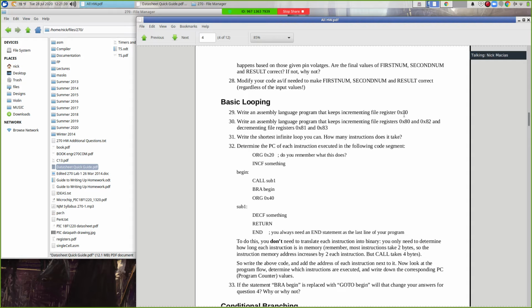If you're writing an entire program yourself, you get to do things like include directives and set up ADCON1 and all that kind of stuff. But when you're asked to just write something that increments a location or adds 2 locations, don't change those locations. Don't take it upon yourself to initialize them or put them in a loop or something like that.